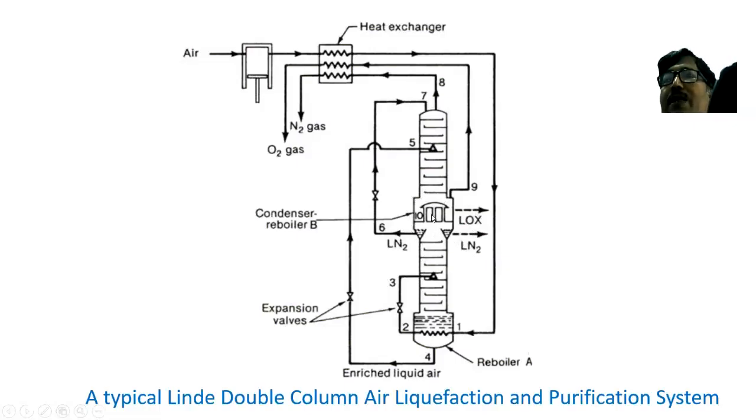So in this section, it will be condensing nitrogen into liquid form and vaporizing oxygen. When it is vaporizing liquid oxygen to vapor oxygen, it will be acting as a reboiler.